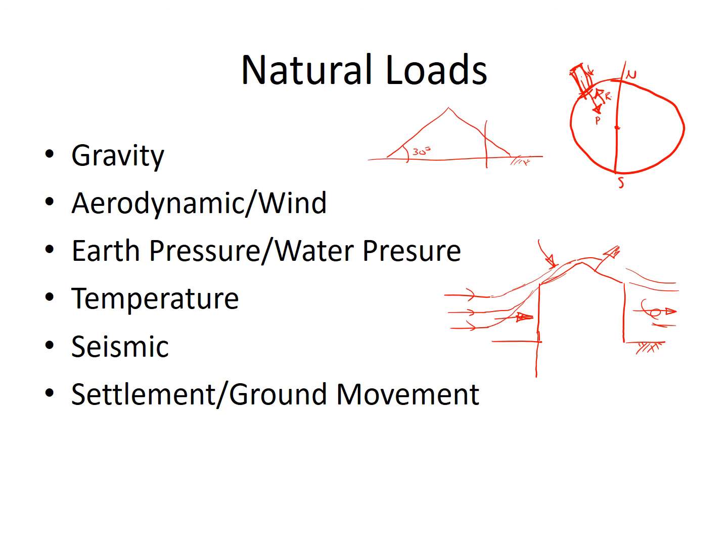we have a basement to this building that we're designing, and that basement goes below ground level, so we're down at a sort of formation level here, there will be earth pressures, and those earth pressures are essentially, if this is the retained part of the fill, that gravity will cause the earth in this region here to exert a force that acts down on the wall in this direction here.